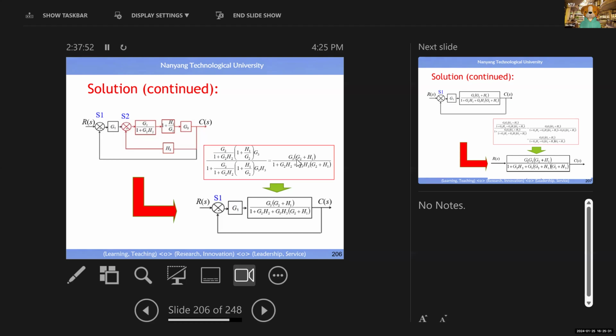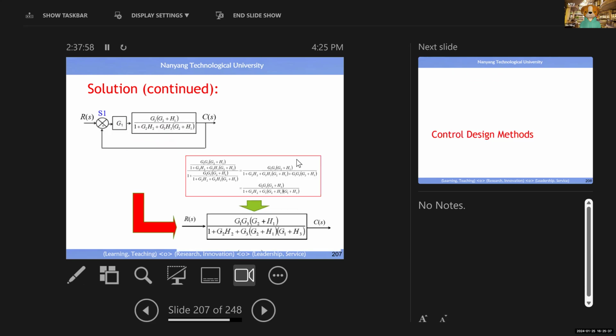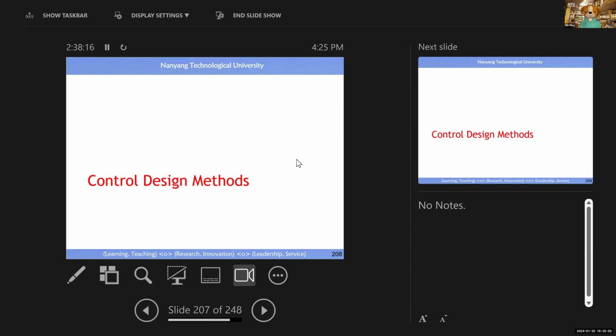Again, this is another standard feedback control loop, right? Replace it by the equivalent transfer function, forward path over 1 minus loop. Simplify it. Finally, you see, without solving any equation, you can reduce any complex system into a single module which has an input and an output. You see the power of Laplace transform.